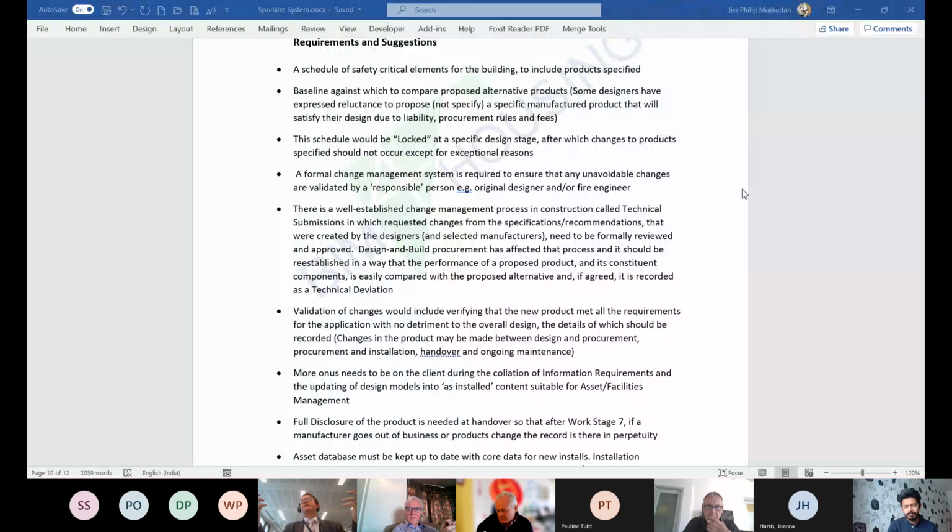But residential, generally you'll bring them on straight away, because the residential sprinkler layout affects the whole apartment. Whatever that is, you're stuck with. Does that make sense? When you say straight away, you mean at stage 3? Any good developer in residential will bring a sprinkler contractor on for the apartments at stage 3, before the design's finished, because it affects your whole apartment layout. Architects want things linear, and sprinklers don't do that in residential. They go where they've got to go.